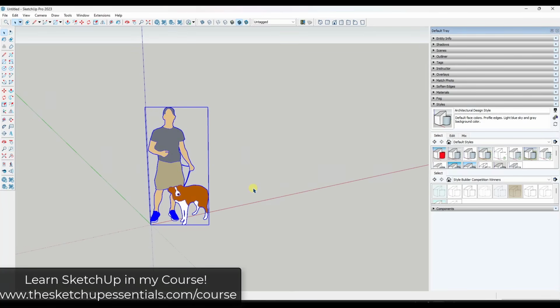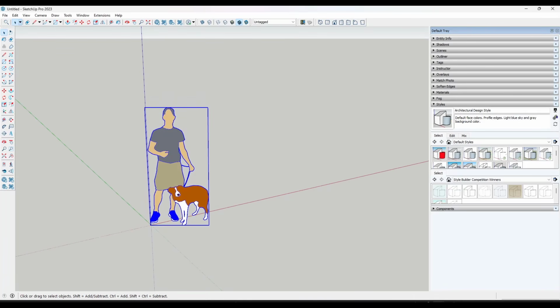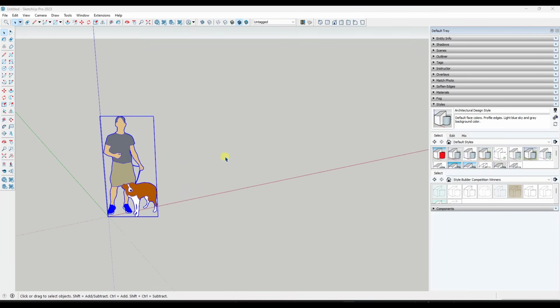And so the first thing we want to do is start by roughing out the back of our cabinet. Because when you think about it, the cabinet is the box that you create plus the doors. In this situation, we're going to start by roughing that shape out, simply drawing a box. To do that, I'm just going to use the line tool, so I'm going to tap the L key on my keyboard. I'm going to single click and draw a box that's the depth of the cabinet I want to create. In this case, it's going to be 2 foot 3 inches deep right here.